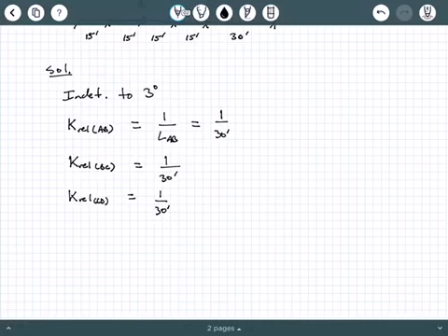Now we need to get our distribution factors. Okay, now question, how many distribution factors do we have per span? Do we have 1 per span? No, we have 2 distribution factors per span, 1 relative to each end, okay? So make sure you know that 2 distribution factors per span, 1 relative to each end.